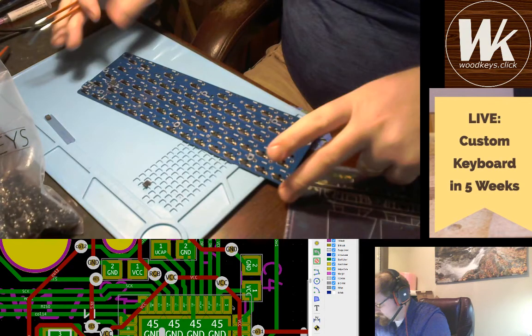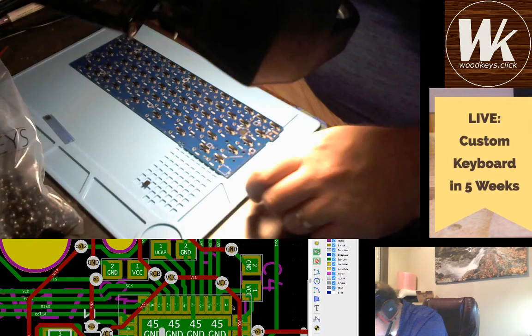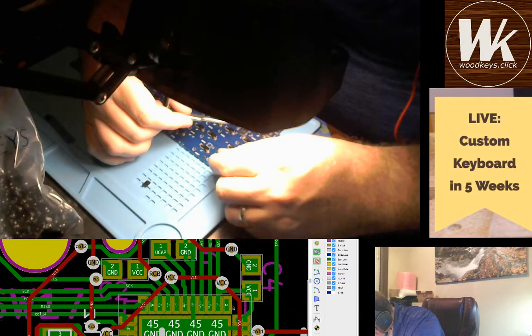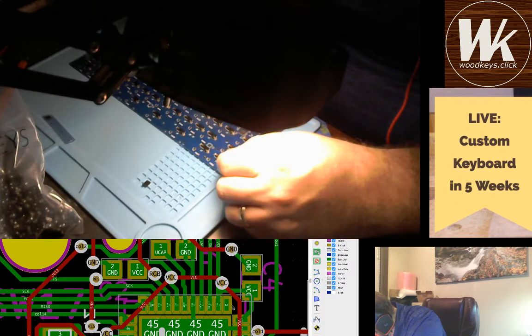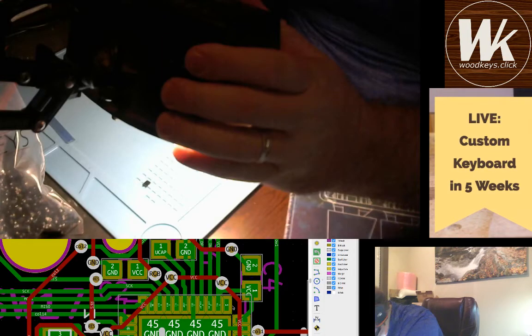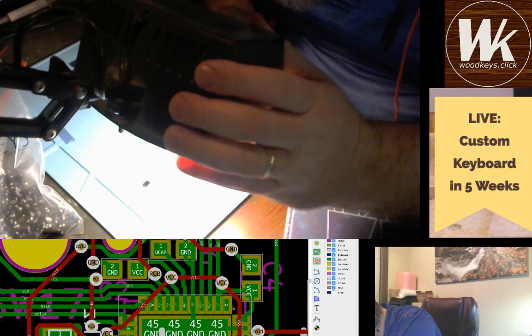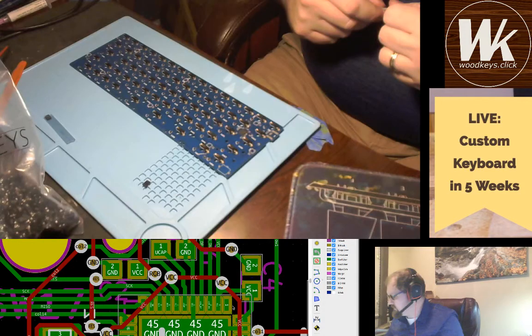I'm going to spin this around, put it right in front of me and check it, make sure it's aligned. Because this is a very fine pitched QFN package that I don't want to have bridges and pins that aren't aligned properly and all that. Okay, looks close enough.